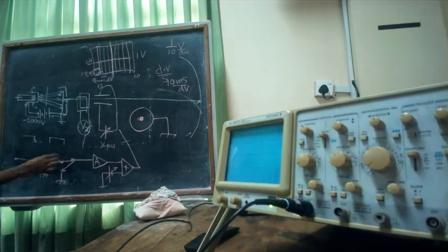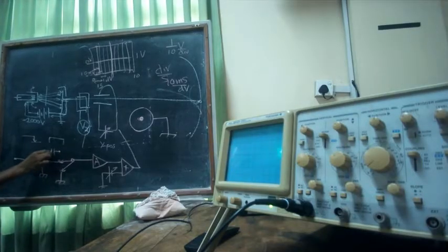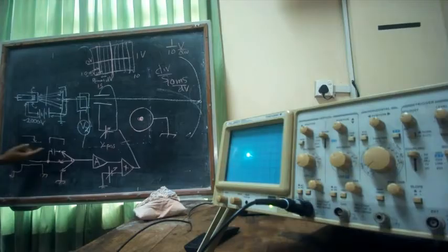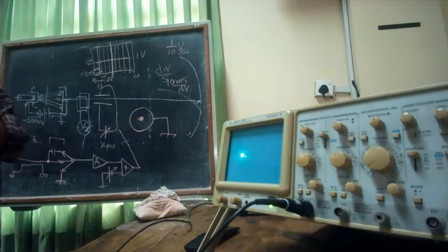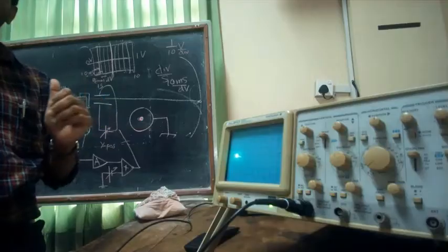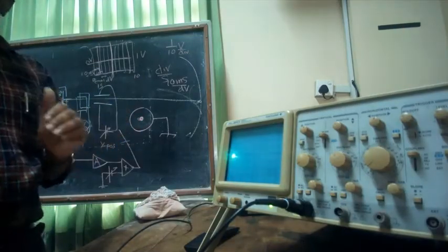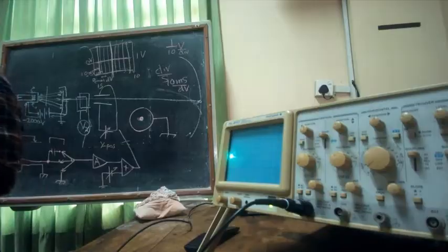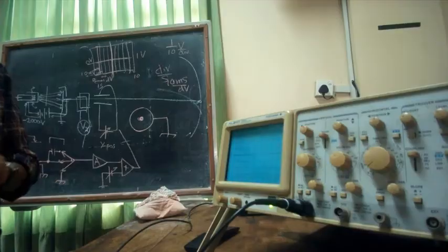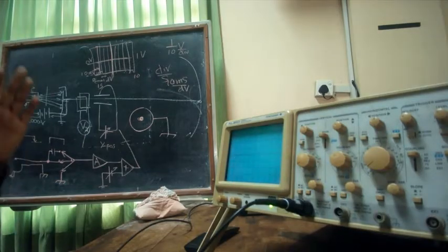AC means you have a capacitor like that. So you are connecting it to this probe tip through a capacitor. Later on you will learn that capacitors block DC components. They charge up to that DC value and after that it doesn't change. But AC components, the values that change, can go through the capacitor without any issue depending on the size of the capacitor. So that is what happens.